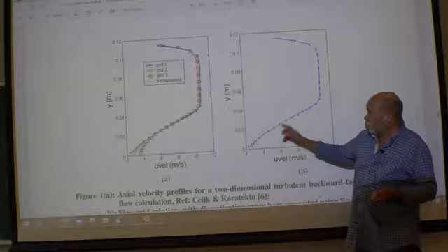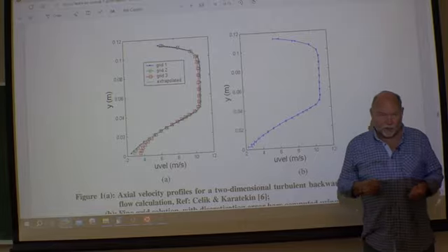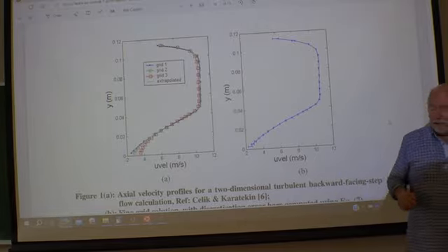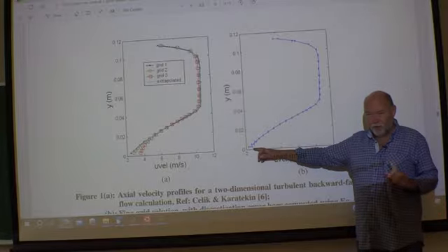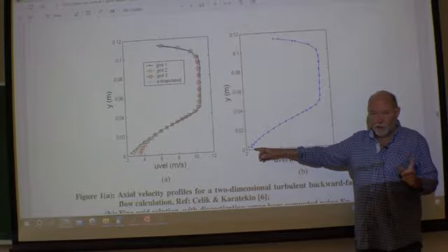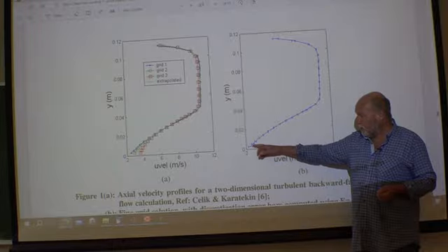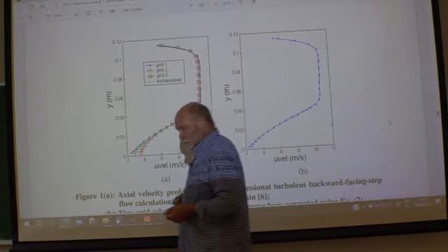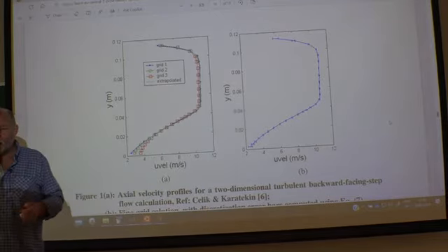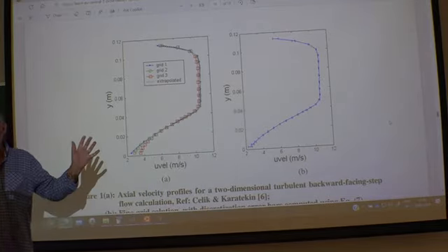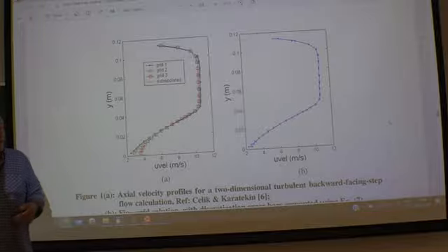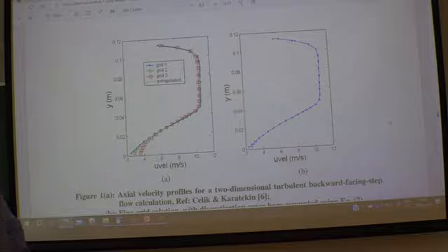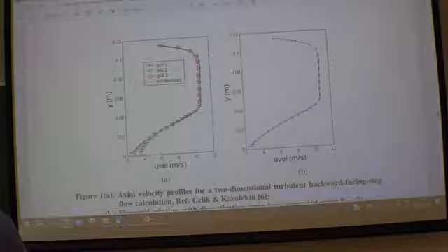Anyhow, when you have the velocities for all 3 meshes in all these points, you can evaluate the local small p, the apparent order of your numerical scheme. You will get a different value for all these points. And then we cheat. We create one average value, and then we have one p. Done. So that is the way you create a profile. That makes life a little bit easier.